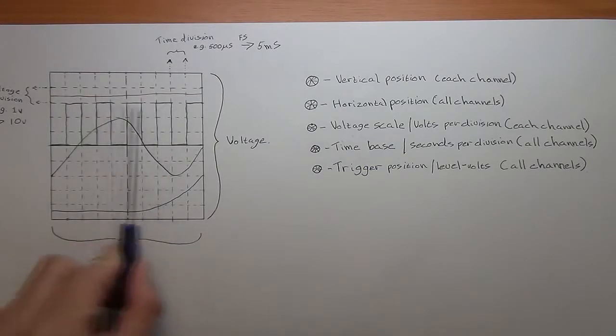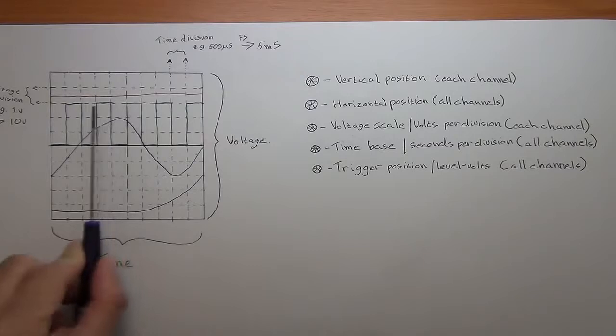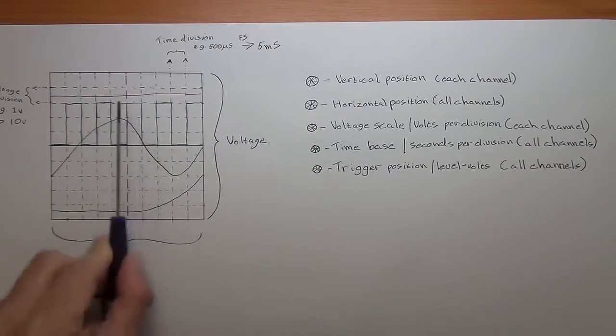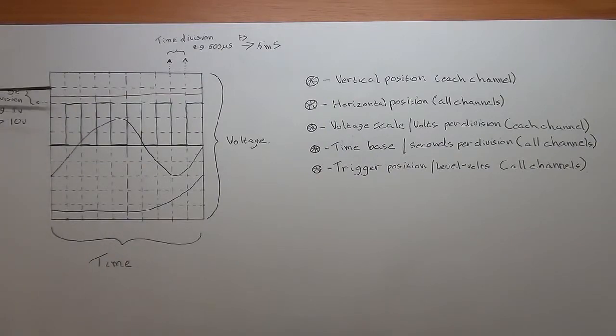And that can be rather difficult to evaluate and have a look at if you want to keep it live, if it's jutting around and moving around. So what your trigger does is you then set a level at which you want your scope to capture that signal. And it's adjusted down on your voltage division. You move your trigger down to the middle point of your signal.